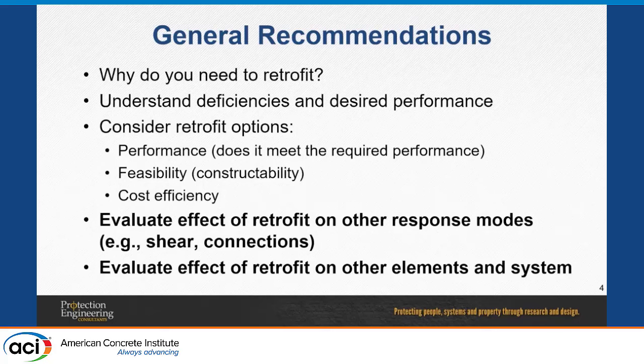It depends on whether you are working with a DoD project, a VA project, or a GSA project, and whether it's explosive safety or petrochem. Make sure you know the reason you want to retrofit. Is it because of flexural deficiencies, or shear deficiencies? Are you trying to protect the component itself, or you don't really care about the component itself, but about what's behind that element, behind that wall? You have to understand that.